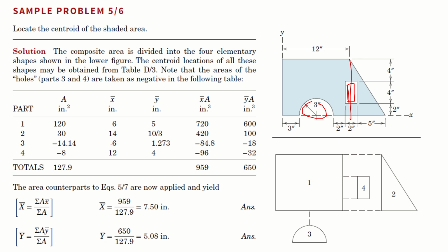Here we can find the area of each surface, that is 10 by 12, and then the positions. Because it is symmetric, we can find the x prime and y prime of each surface, and we can find the corresponding centroid along x and the overall area as per the formula given before.